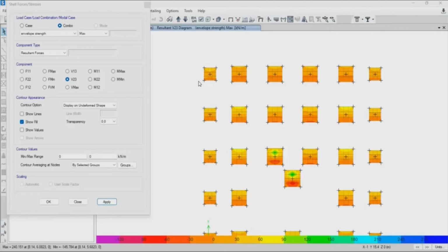Or let's say if you can't increase the thickness of your footing, then you have to provide what we call pedestals. Okay, you provide pedestals so that the column is going to be resting on the pedestal, then the pedestal to the footing. The pedestal is going to try to prevent the punching effect from the column to the footing. So you can either increase the thickness of the footing, and if after increasing the thickness the column is still punching through the footing, then you will need to introduce pedestals. Okay, so this is how you can tackle the punching shear and also the one-way shear check.